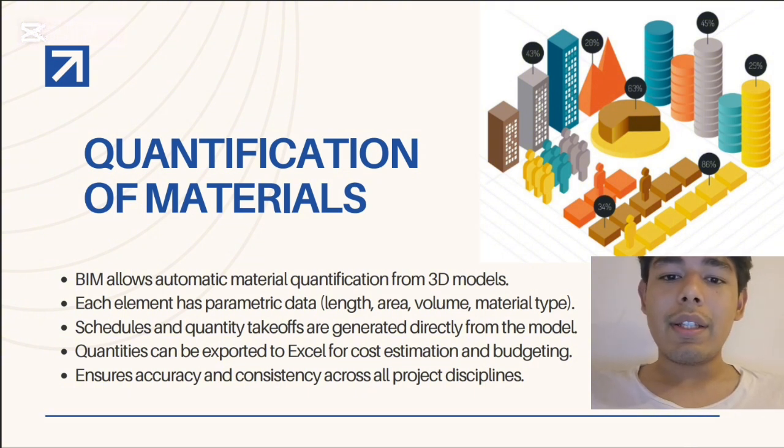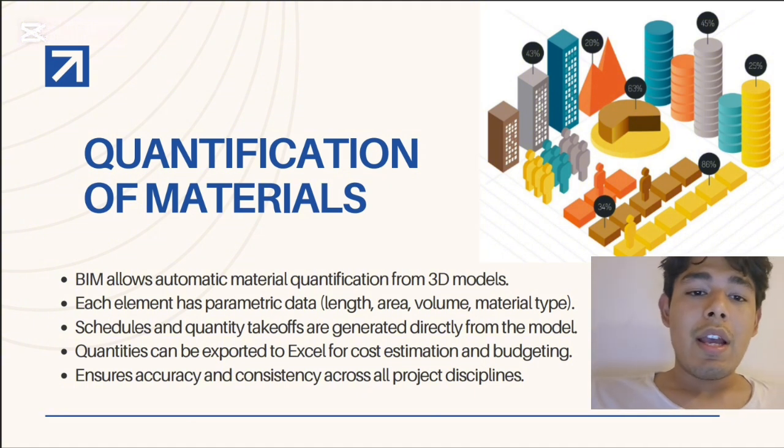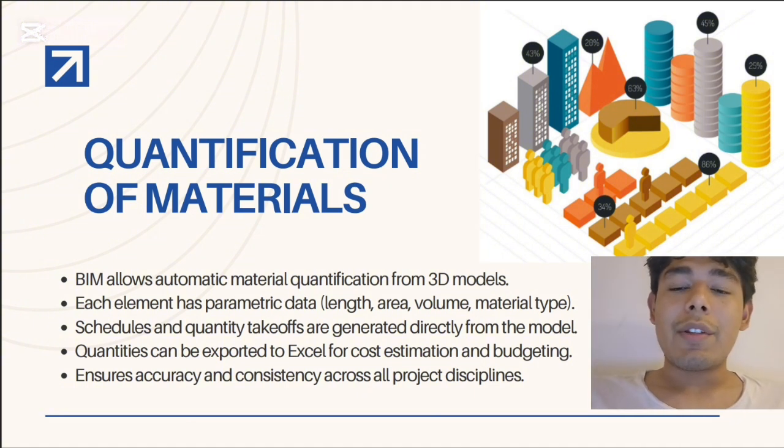Schedules and quantity takeoffs are generated directly from the model, and quantities can be exported to Excel for cost estimation and budgeting. Ensures accuracy and consistency across all the project disciplines. That's all about quantification.